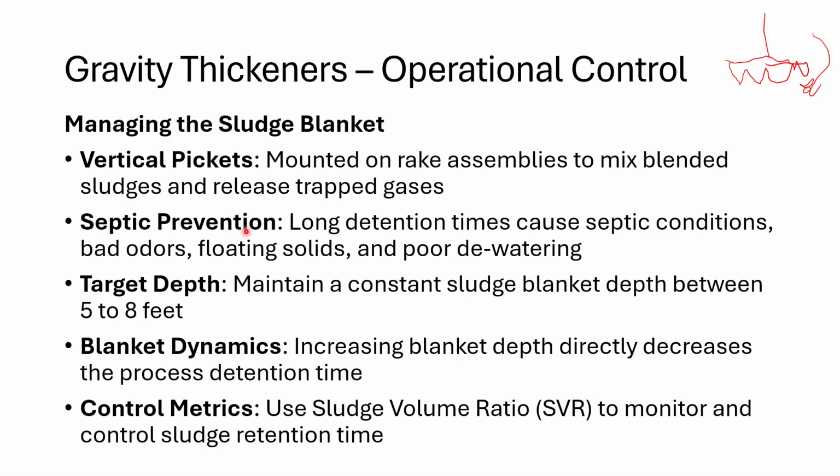Okay. You also want to eliminate those floating solids we talked about. If your sludge goes septic or anaerobic, it's going to eventually put those sludge particles, that flock that form the sludge, back into solution or suspension, and we don't want that. Also, it's going to lead to poor dewatering.